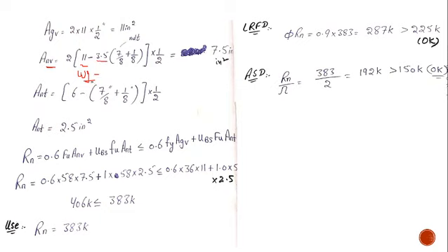It means 3.5 bolts will appear along this path. 7 by 8 inches is actually the dia of bolt, and 1 by 8 inches is allowance, and this is thickness T. So it is very simple. I have multiplied it with 2 because we have two paths along shear. 11 is the gross width and 3.5 bolts are involved. I will show you how.